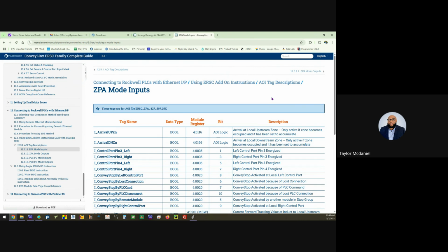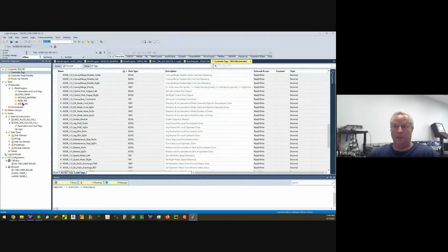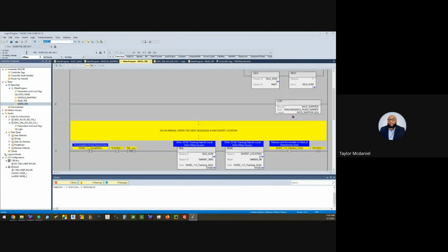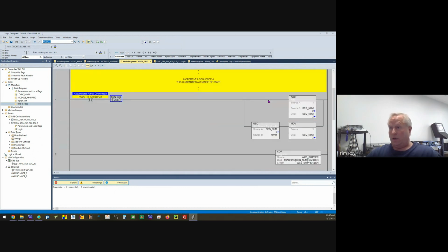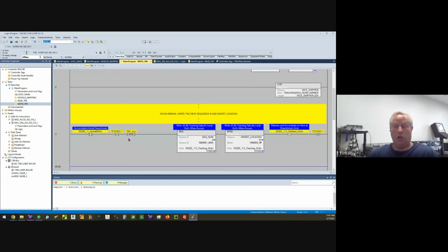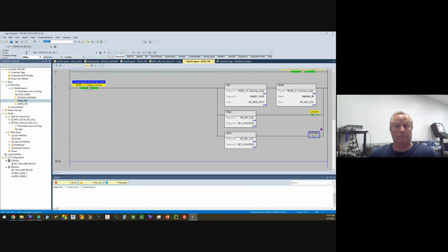But for the most part, I'm getting the information from WCS, and I need to be able to track it along the zones. That's one of my main concerns. That's exactly what we just did with these read and write tracking data. Yep. These simple rungs. So we have 4 rungs to accumulate and write, and 2 rungs to accumulate, read, and make a decision.